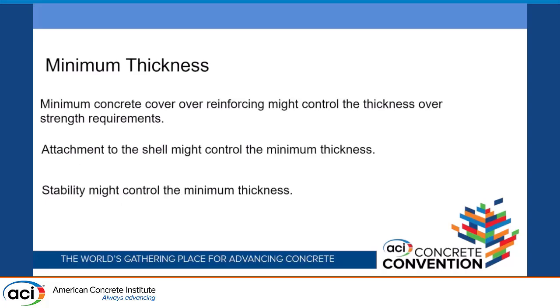We'll talk a little bit about minimum thickness. So if you're designing a beam, how do you get the minimum thickness? You can look at, for this span, we have to have a certain thickness, or else we have to calculate deflections, right? Or we need this much depth to put our steel in to get the strength up. Okay, so it's pretty straightforward.